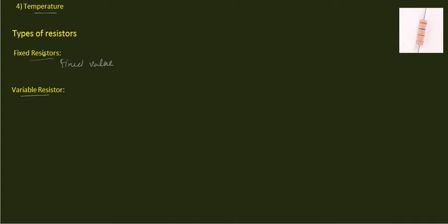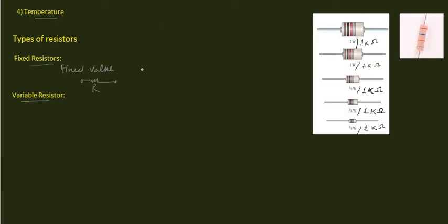The symbol for the representation of a fixed resistor is the same as that used for the definition of resistor we used earlier. There are two main points you need to remember about the fixed resistor. The first one is that in a particular style or manufacturer, by increasing the size of the resistor, the power or wattage value of the resistor will increase, but it does not affect the value of resistance.